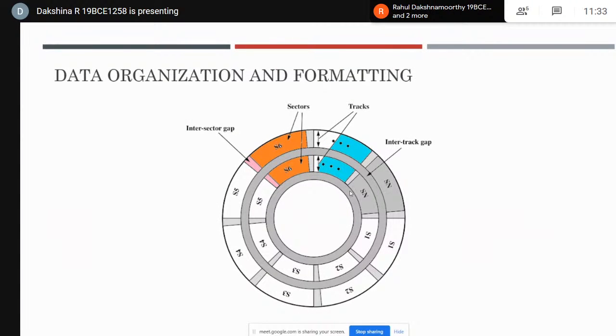The data is organized on the disk in the form of a number of pie-shaped sectors and tracks. The tracks are divided into sectors that contain blocks of data. All read and write operations on the magnetic disks are performed on the sectors. The floating heads require very precise control to read or write data. Each track is the same width as the head, and the head needs to locate sector positions within a track. It's required to know the starting point on the track and end of each sector.